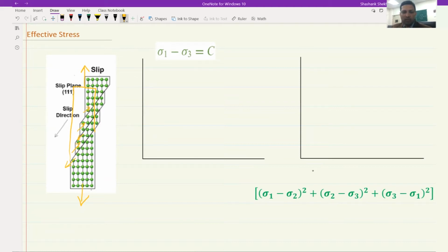And therefore, the stress that we actually require is much lower than the theoretical stress, which we will also look at when we introduce the concept of dislocations. It is also the reason that last class we saw that in the yield locus, some stresses higher than the yield strength of the material can be present in the multi-axial stress state, and still yielding will not occur. That is still possible, because what we were talking about is the normal tensile condition.